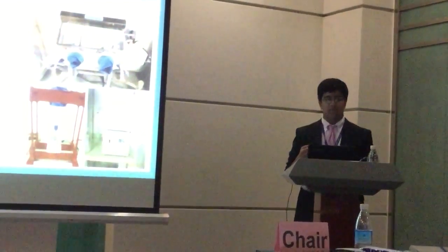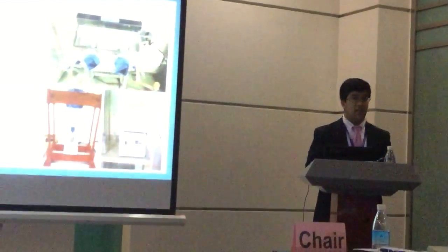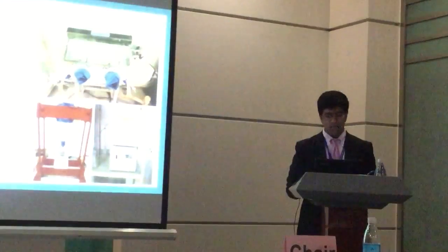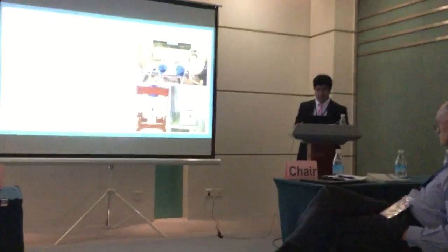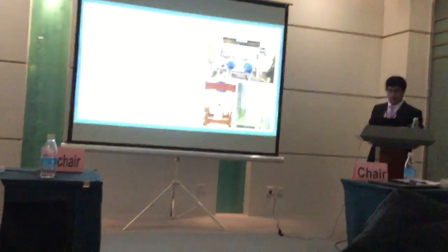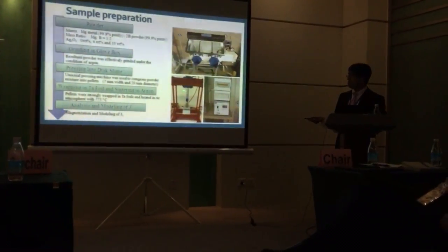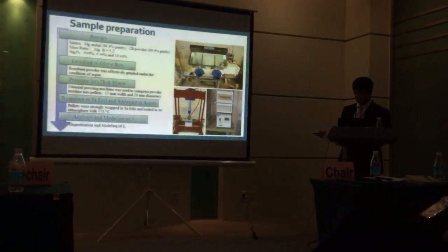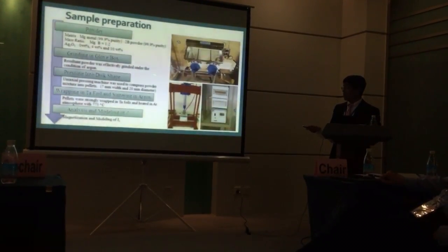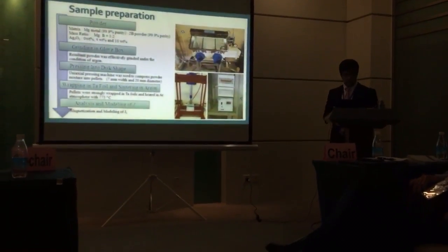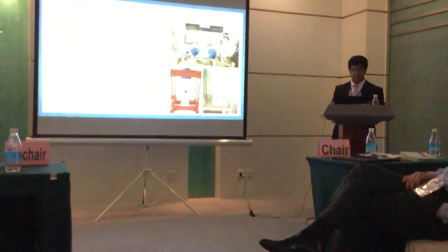After definite proportions of the sample were prepared, the grinding had to happen in the glove box, and this was ground in an argon atmosphere. This is a simple picture of where the grinding process happened. After the grinding, it is necessary to use the uniaxial pressing machine to create the disc shape of the sample. And lastly, it was wrapped in Ta foil and sintered in argon, and the temperature utilized for the sintering process was 775 degrees Celsius.